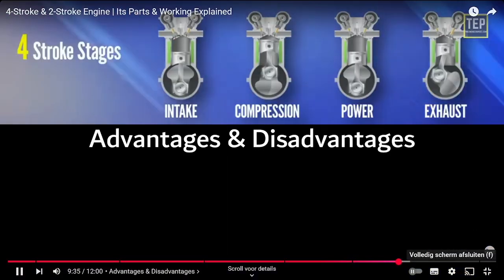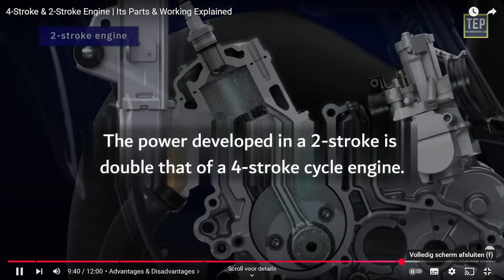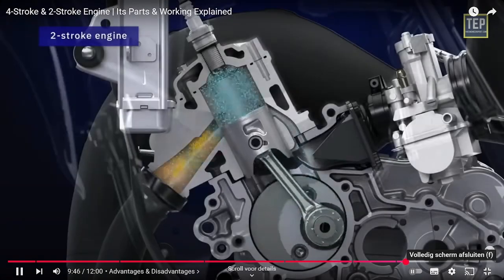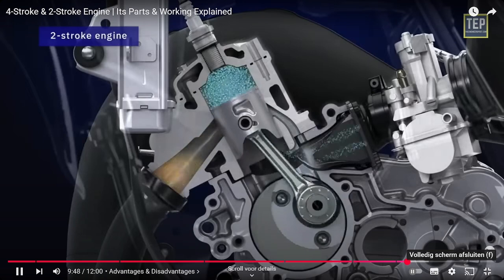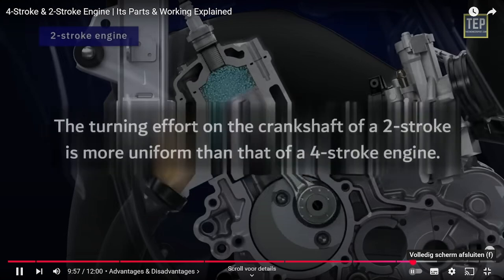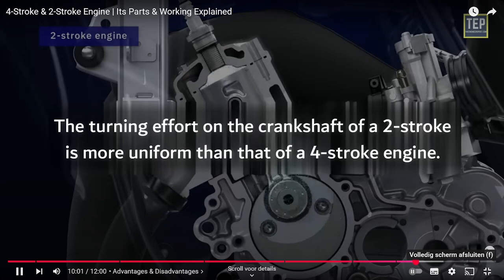Now let's look at the advantages and disadvantages of the four-stroke engine over the two-stroke engine. The power developed in a two-stroke is double that of a four-stroke engine. Due to shortening of the effective stroke length of the piston, and due to the fact that the engine has to operate the scavenging pump, the actual power developed in a two-stroke, instead of being double, is 1.7 times that of a four-stroke engine. The turning effort on the crankshaft of a two-stroke is more uniform than that of a four-stroke.